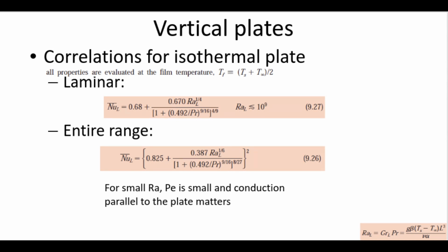If Rayleigh number is pretty large, which term is larger, this constant term or our Rayleigh number term? Your Rayleigh number term dominates for very large Rayleigh number in turbulence, and you have 1/6 here, then the whole term squared. It is consistent when we have turbulent flow. Your exponent is 1/3. Those equations are not random.